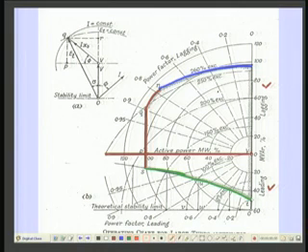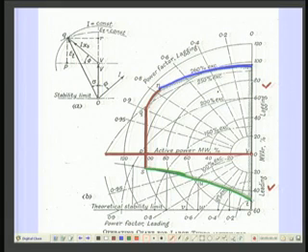One segment of the curve represents the stability limit consideration, and this is basically when operating in the leading power factor condition. This vertical line shows the real power output condition, that is the turbine limit. This segment Q to N corresponds to the stator current limit, and from N to M, it represents the field current limit, right.